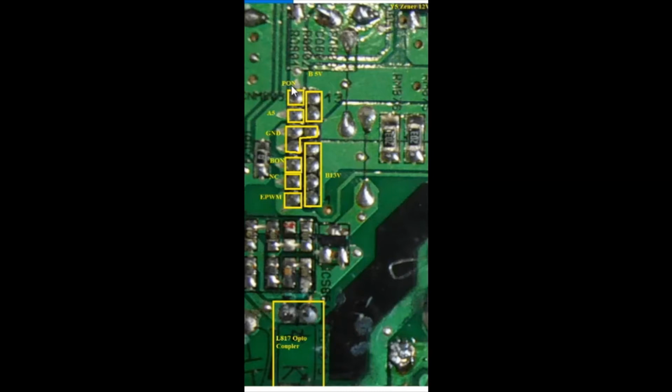pin on the connector. This is the power on connector pin. If you want to power up this PCB, when you switch on, if you disconnect the PCB and just keep it as is, the low side voltages won't get activated. This P-on signal is needed, which should be connected to the 5-volt to operate the power supply.